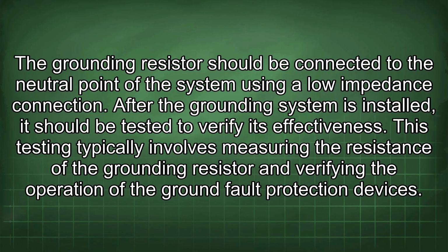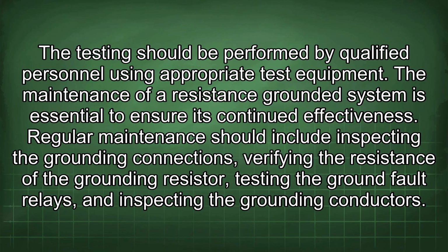After the grounding system is installed, it should be tested to verify its effectiveness. This testing typically involves measuring the resistance of the grounding resistor and verifying the operation of the ground fault protection devices. The testing should be performed by qualified personnel using appropriate test equipment.